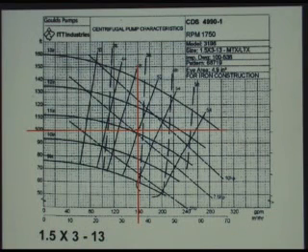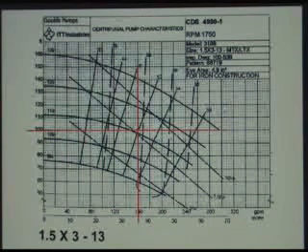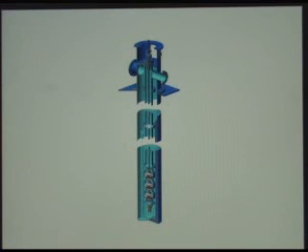So those are things that we can do to try to get a pump to fit what we need it to do. Now, if it turns out that there's just no way that we can do anything, we can't raise the vessel, we can't get a slow enough pump, we don't want to put a cooler in because the flow rate's so high, we don't have enough cooling water to be able to cool the pumpage down, what you end up having to do is put in what we call the vertical can pump.